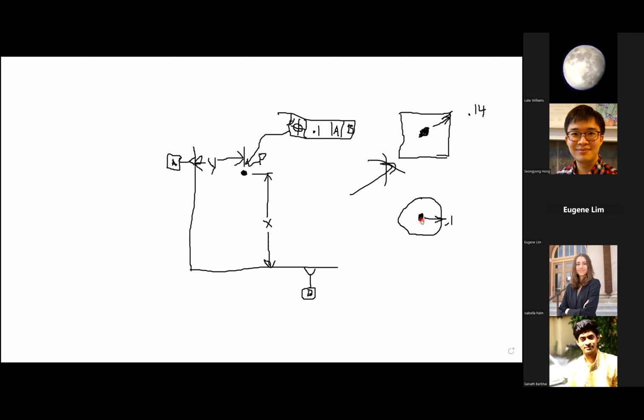So the last couple of things we need for this drawing then is we need to show that these dimensions, X and Y, are subject to this control feature. And the way we do that is we sort of put a box around it like this. And so that says that these dimensions are controlled by this control feature that we placed right here.